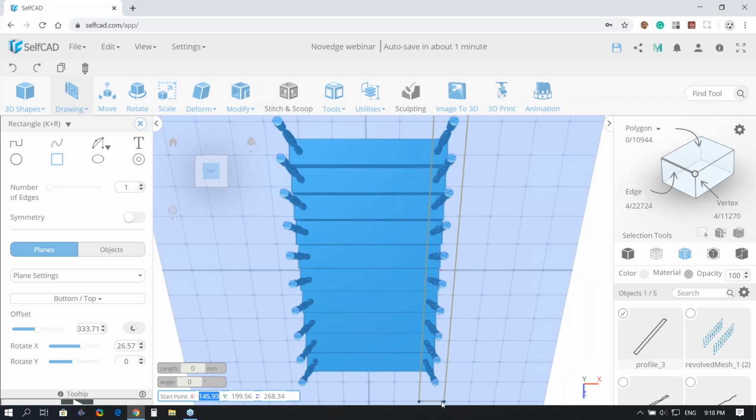Okay. So I'm using this and now I have this. So now what I'm going to do is, this looks like it's positioned correctly, so I'm going to extrude that. I can fill polygons now and then extrude, but on a simple shape like this, you can just extrude it as well. So I'm going to extrude it by 20 and now I'm going to fill polygons. I'm going to fill it and now you got this positioned relatively okay. And I just need to make a copy of it.